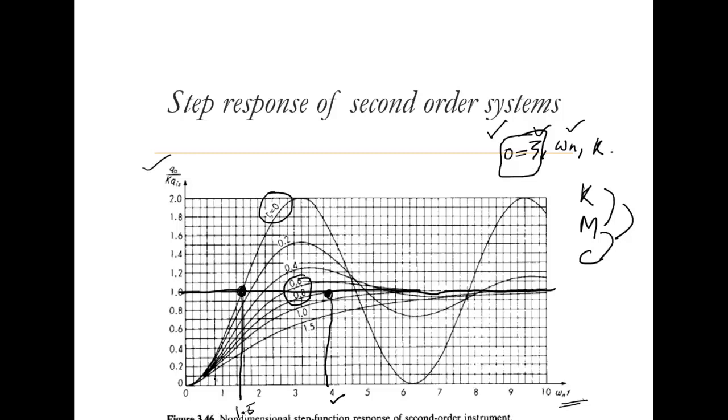Otherwise, we have some systems where we have over-damped systems, where zeta is almost equal to 1.5 or even 1, where it almost doesn't even oscillate, but it maintains a constant gap between the input and the desired output and the output by the instrument. There are systems called critically damped also, where it almost touches the line, but sometimes we compromise with all such factors and then try to put zeta at around 0.6 to 0.8, which is the most desired value.